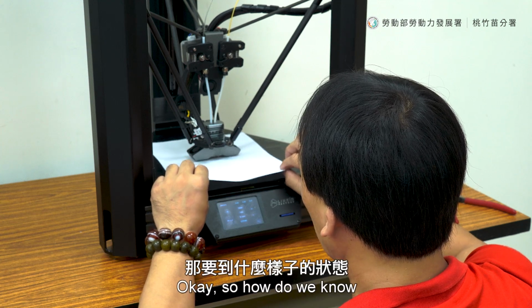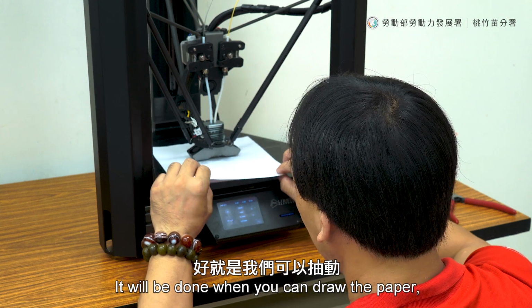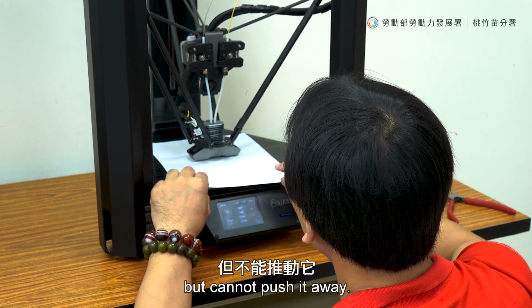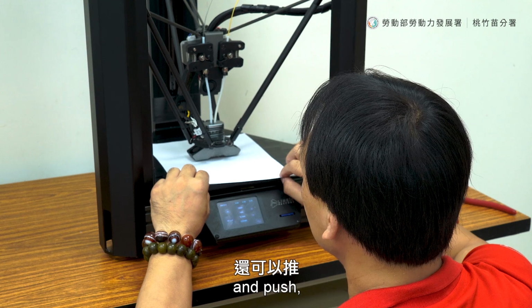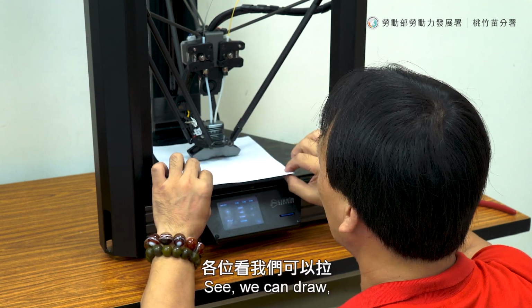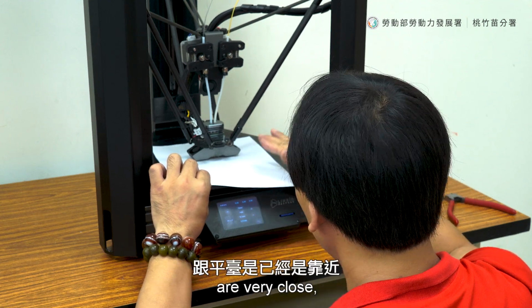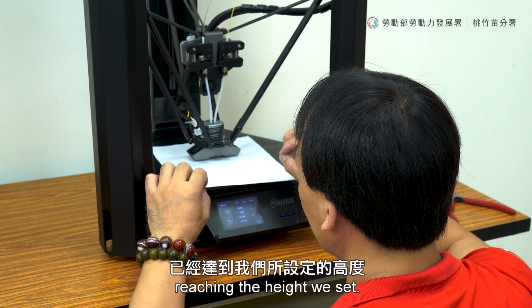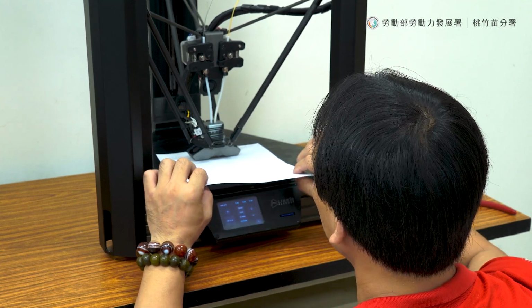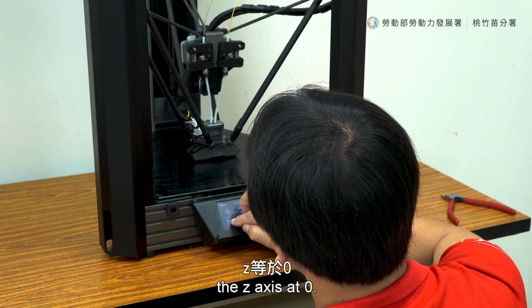So how do we know it's reset to 0? It's done when you can draw the paper but cannot push it away. Now it's okay to draw and push, so we need to go down. Okay, it's a 0, see? We can draw but it arcs when you push. This means the nozzle and plane are very close, reaching the height we set. Now we can draw the paper away, setting the z-axis at 0.